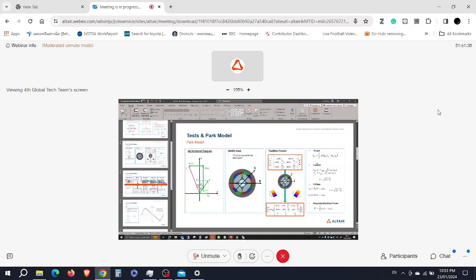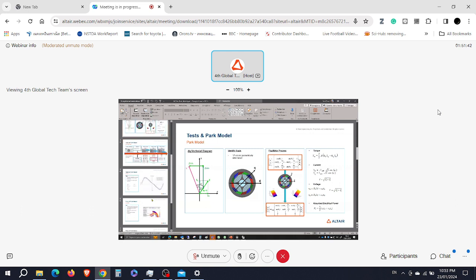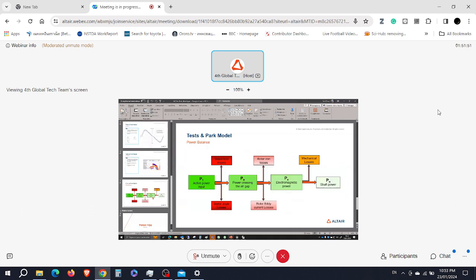We have the possibility to compute the current, because this is what we impose. We have the possibility to compute the torque and so on. So we have all the elements to make our computation of the joule losses on the stator winding, the iron losses, thanks to the Bertotti model and the Bertotti coefficient already computed when you defined your materials.